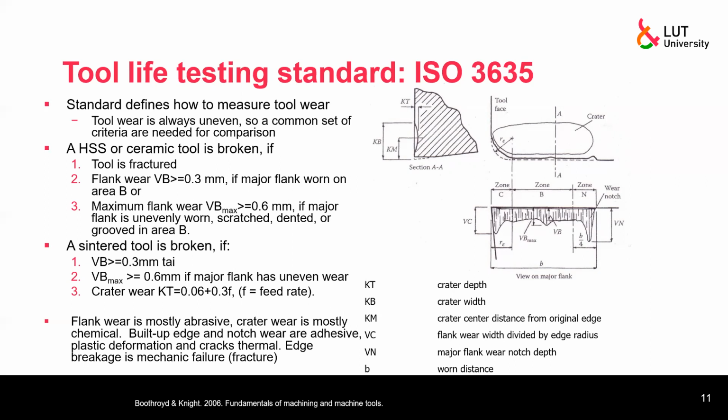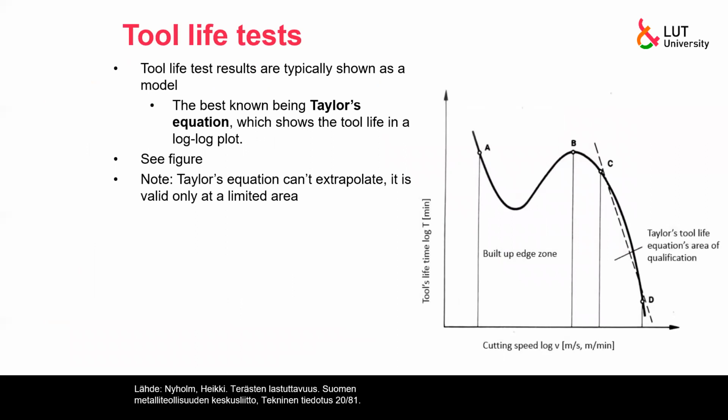And how to model it? Well, okay, one more. Actually, it is just a part of the wear model. In some parts, if we are going too low, there may be built-up edge, which means that we're having material that doesn't flow properly on the tool, and it gets welded on the tool. That causes trouble as well. So we're having troubles there.